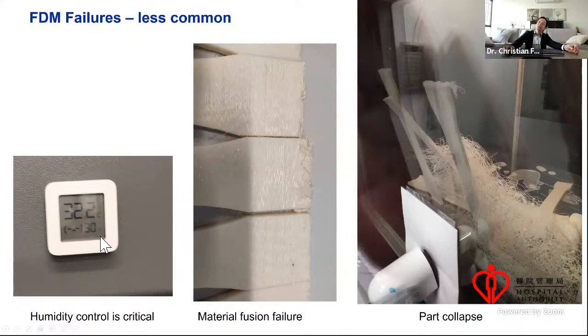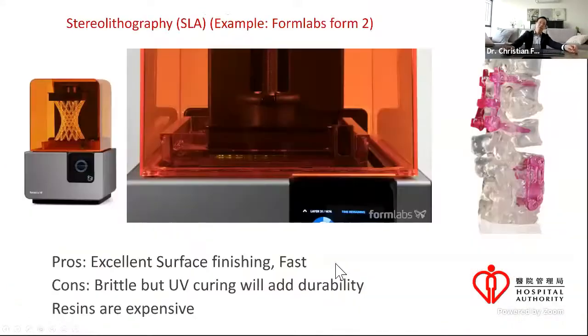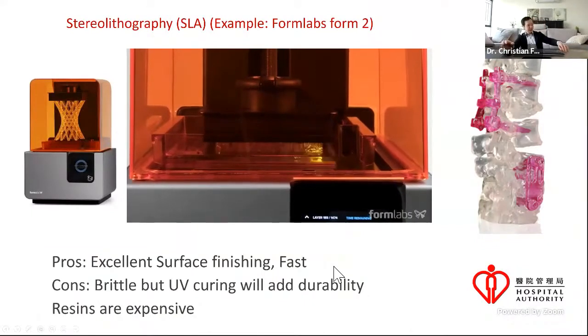So what we discover over years is when there's more humidity, it actually affects the printing quality, because the water gas bubbles would form steam bubbles and actually destroy your printing product. So sometimes the part will collapse mid-print and you have to start all over again. And so this is like a total failure of the jobs. They're not as reliable as you would like.